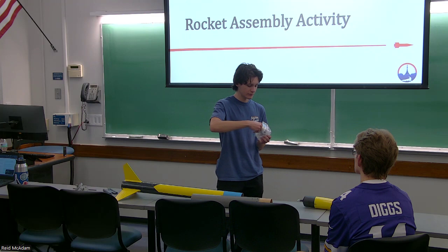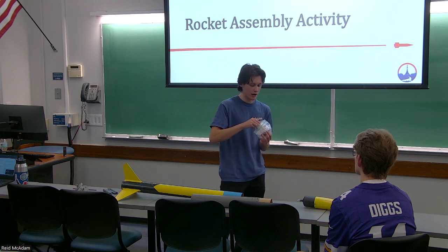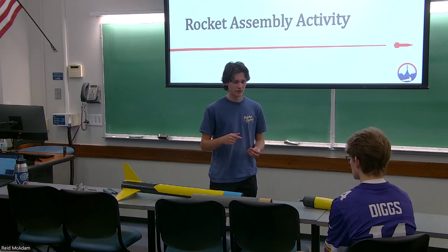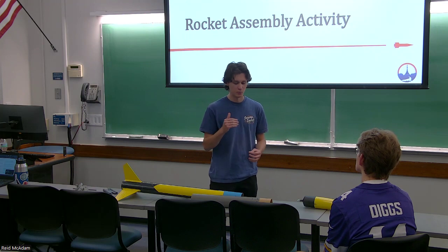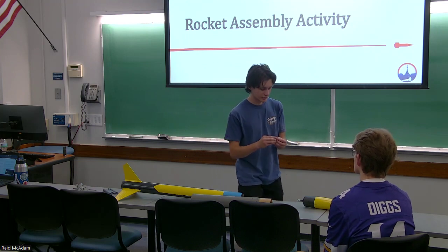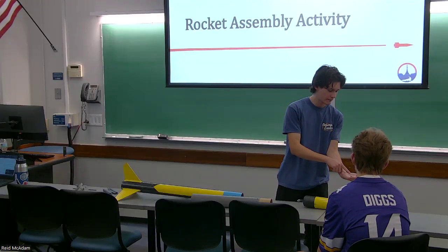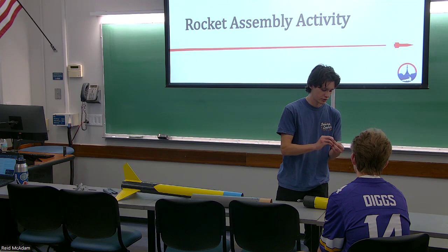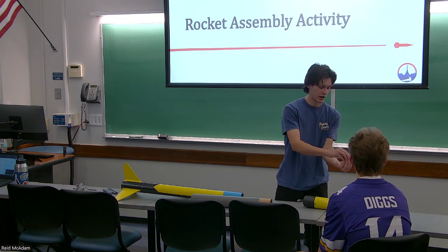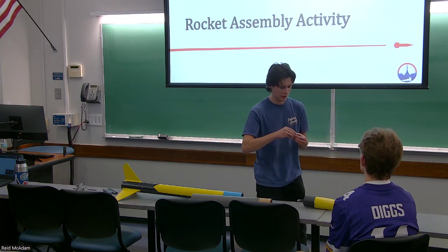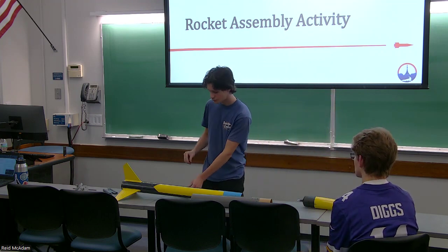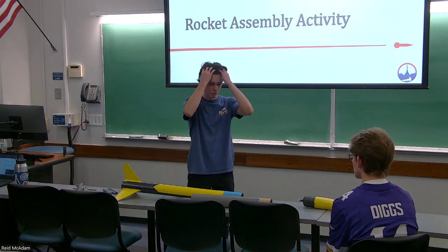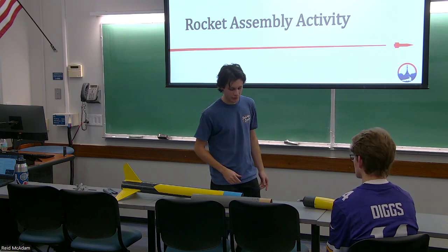When that head piece goes in, it makes the bottom piece kind of flare out so that you can't pull it out. And then also, since the bottom piece is a solid piece, you can't really move it side to side either. You can see right now, the bottom piece is just a straight cylinder, but when I push it closed, the bottom piece flares out. So now if it were inside something, I can't pull it out. I would have to remove the head first. In flight that wouldn't happen because there's not really any flight forces that would remove the head, as long as it's pressed in all the way.